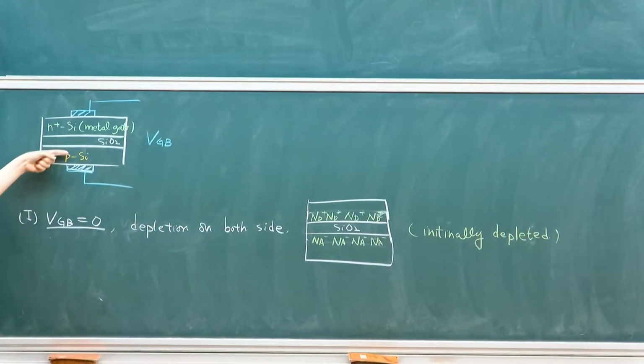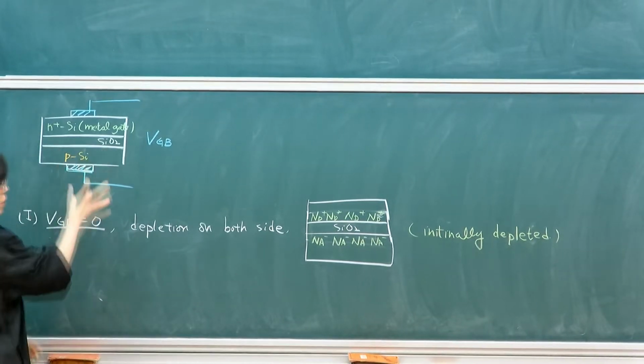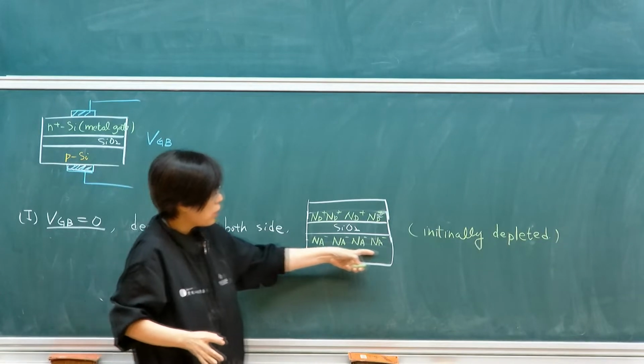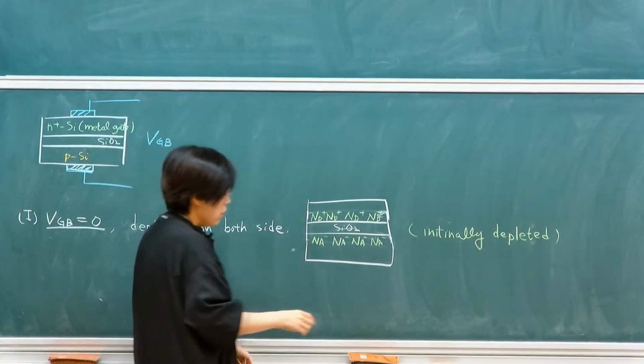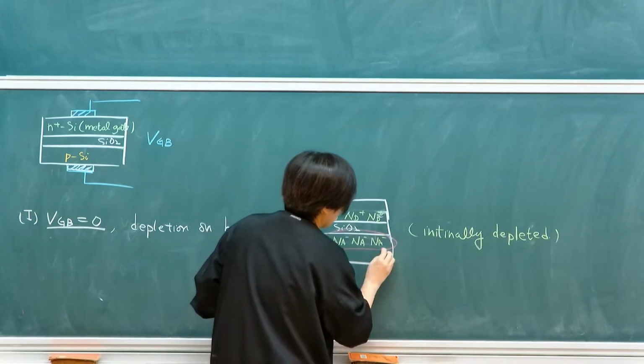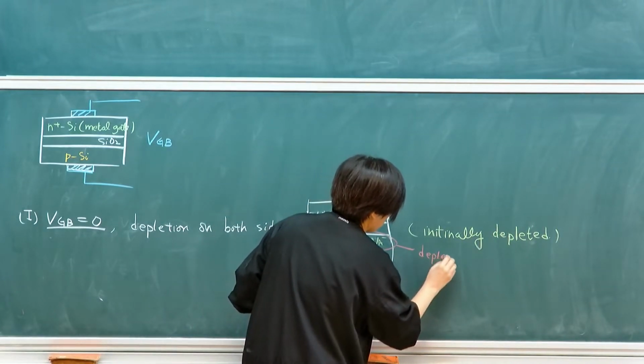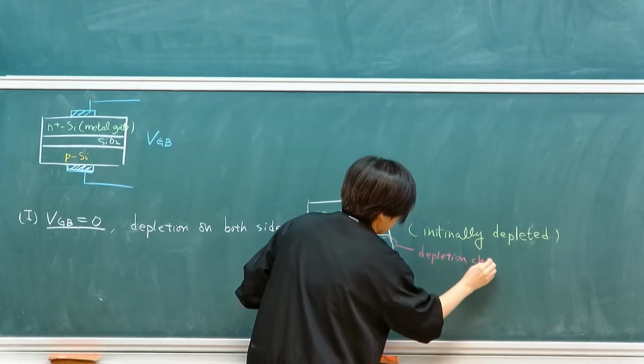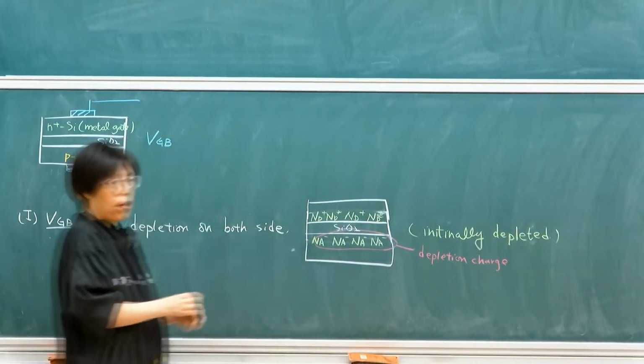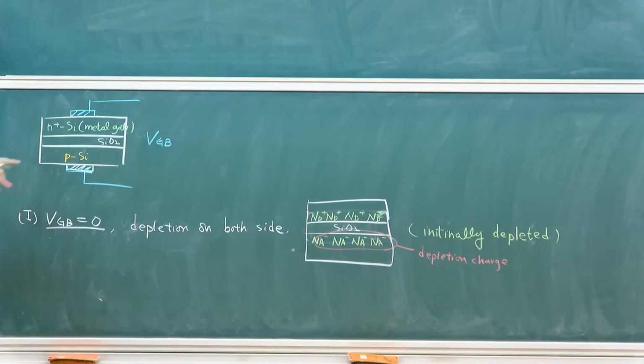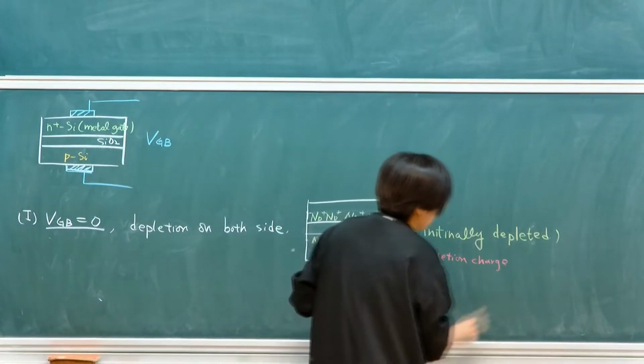Let's say the channel is right here, at the surface. At the surface, underneath the semiconductor, there's only depletion charge. Even though we have charge at the interface in the channel region, it doesn't really conduct current, because the depletion charge, or space charge, is immobile.